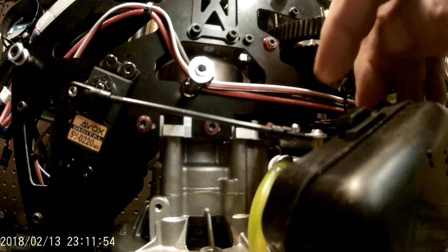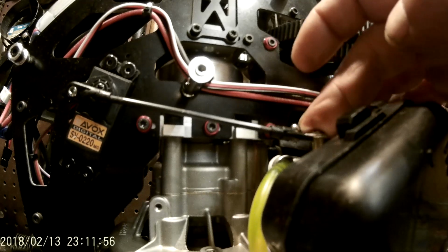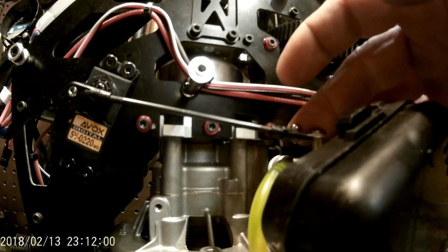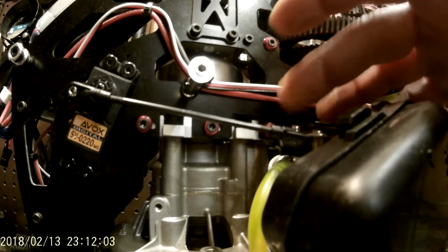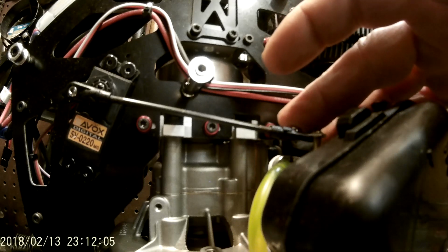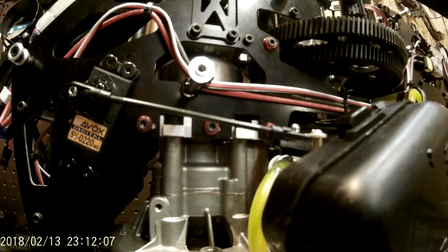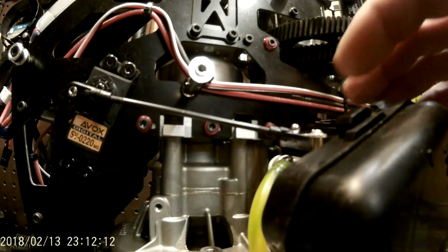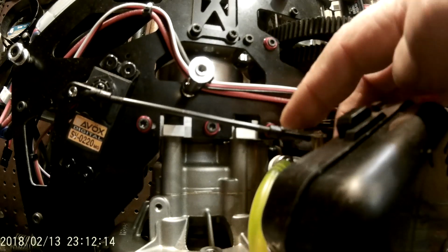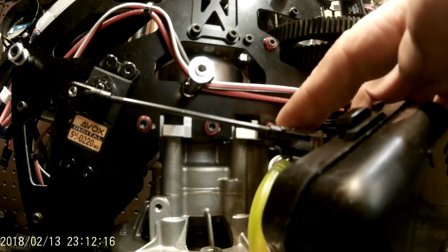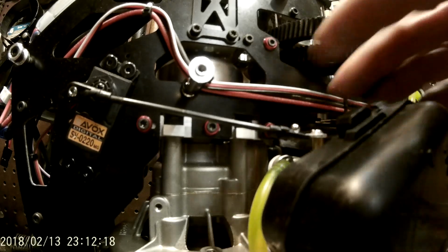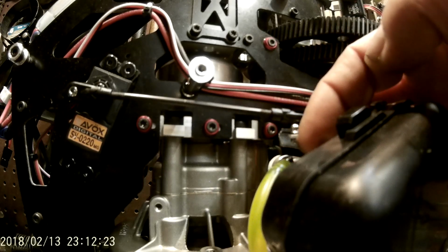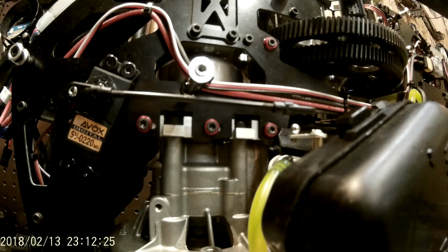And before you do this, make sure that you back out your idle screw on the carburetor so that the throttle plate goes 100% completely closed in the throttle bore. Because that's how you're going to stop the engine with the ArduPilot system. You're not going to use the ignition switch or the ignition kill. And in fact, with a nitro engine, ignition kill won't work. So make sure that the throttle plate goes 100% completely closed, and back the throttle screw out until it does. Now we have to adjust that min value right now to get that link to go on there.